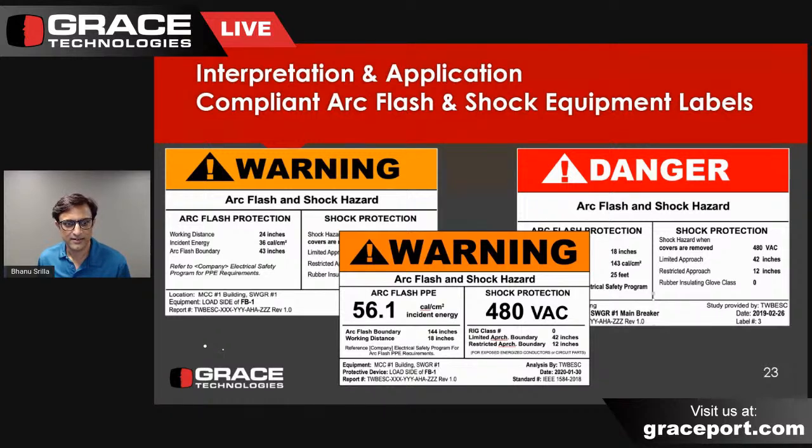So it's the arc flash side that just needs to give the incident energy at the assumed working distance and the arc flash boundary. No information about people. And how often does this have to be done, Terry? Every 5 years, the study should be reviewed, right? IEEE 1584 was published 2 years ago, so existing studies should be reviewed for that reason. And again, later on, we'll talk about IEEE 1584 and some of the specific parameters of concern that the owner of the electrical equipment needs to control.